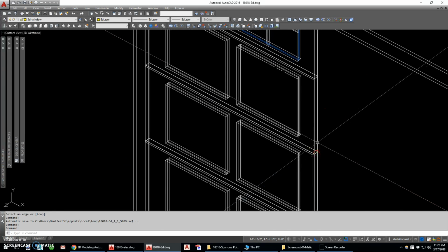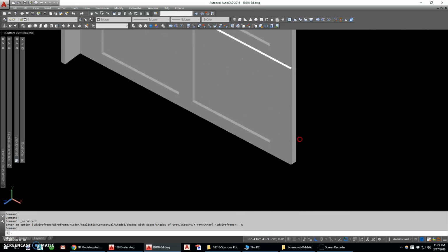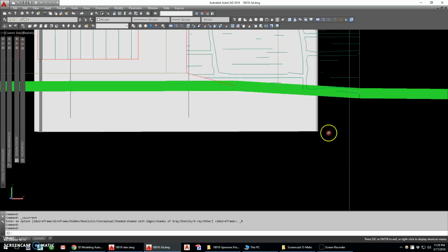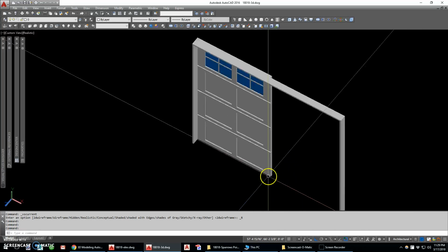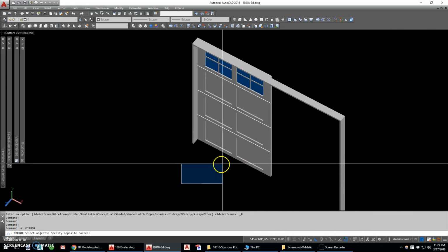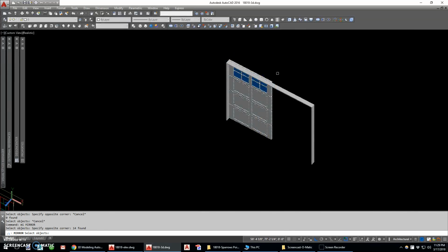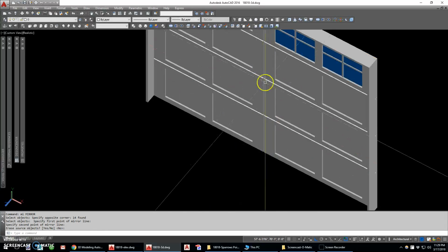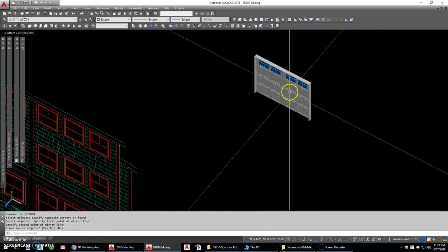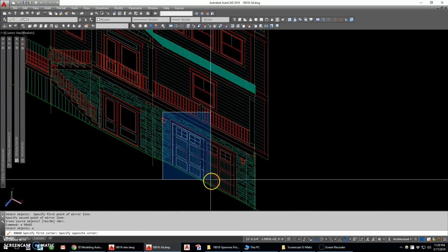And if you look at this in 3D, I was making half the door, but I actually used the chamfer command, which works in 3D as well, to bevel the door. I beveled the individual panels so that when I mirror these over, I have a break between the panels and a break in the center, like the architect's drawings depict.